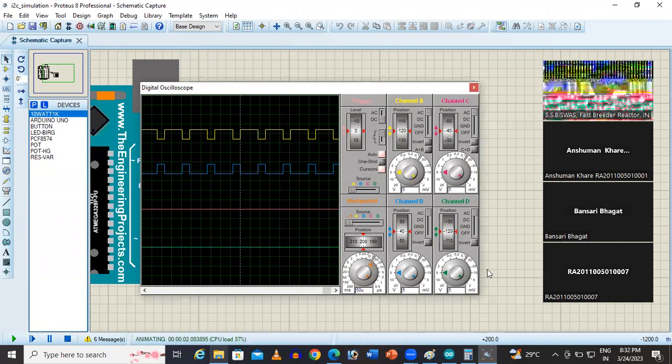And you see, our total resolution is 10 bit, so 300 is given. So it's just around 30%. So you see the blue pulse is giving the non-inverting pulse, and the yellow pulse is giving the inverting pulse.